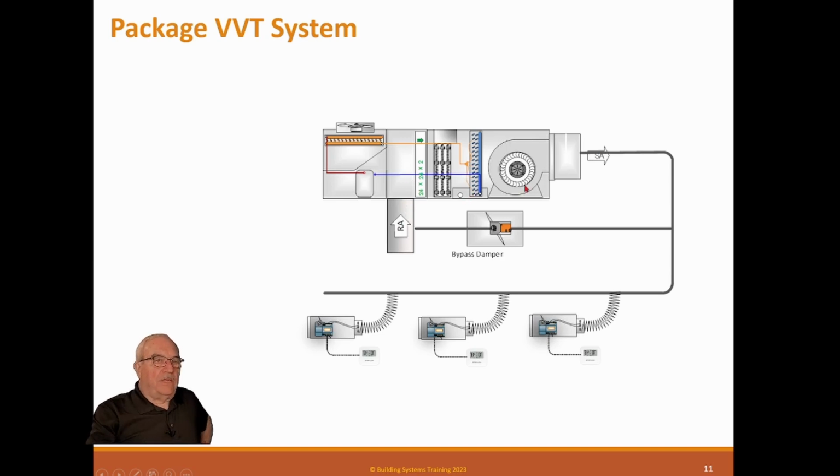And a package unit cannot stand variable flow on this coil for very long. Normal coils are good for about a 30% variance, and after that, you could actually damage the compressor. If liquid refrigerant starts flowing back to this compressor, it will damage it. Now, scrolls are a little bit less susceptible to that, but still, it's a problem. So now, you ask, why are we doing this?